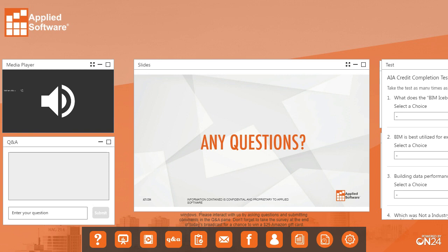For energy analysis, you might have seen one of the slides that was called Insight. Autodesk Insight gives you the ability to go through and analyze a building while it's still in schematic design, and gives you the ability to quite easily change, for example, what type of glazing without physically going through and changing the glazing on your Revit model. Insight through Autodesk is absolutely amazing and really gives you an advanced feature of changing your model without actually physically changing the geometry. And those are just some of the ones that I spoke about during our presentation.